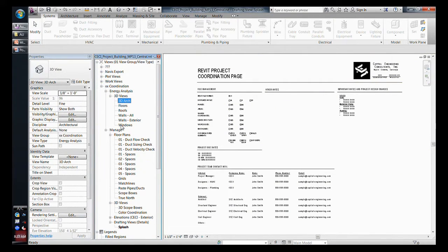And these views here allow me to very quickly check what the architect did with the model. Very often they would, for example, when they're creating roofs, they would not actually use the roof command. They would use floor command. And they have their reasons. The floor command allows them to display certain things that the roof command doesn't. So that's a very common workaround for them. So I can instantly see that, and when I export out to my energy analysis software, that's not acceptable, so I need to remodel the roof eventually. And that's my quick answer there. Do I need to do it or not?